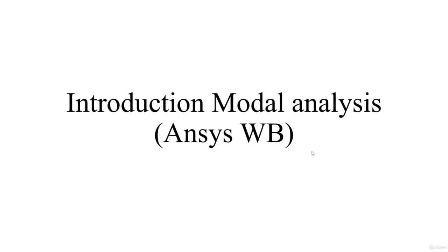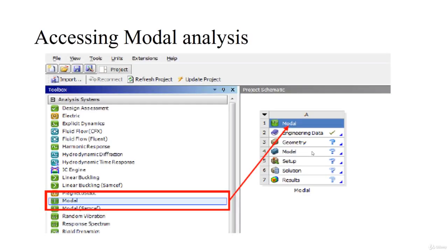In this lecture, I am going to introduce you to the modal analysis and how modal analysis can be performed inside Ansys Workbench. In order to access modal analysis, you need to go to the analysis systems. In the analysis systems, you need to select the modal analysis system and drag it and drop it on the project schematic. As I have told earlier, the steps you need to perform will be from the top towards the bottom.